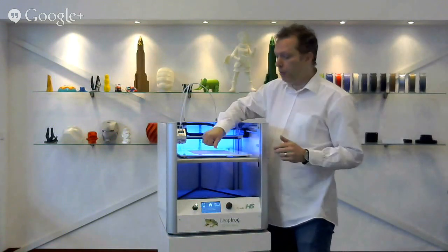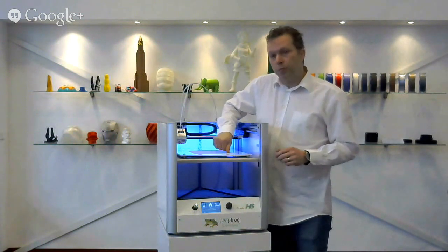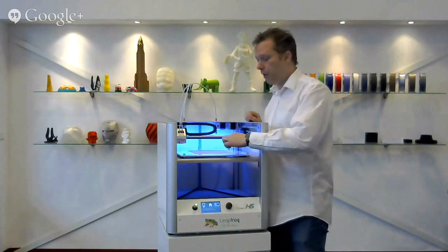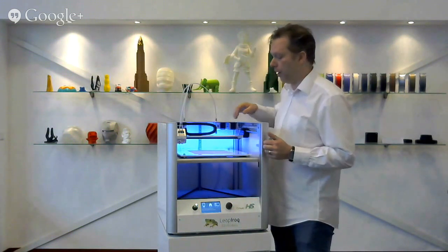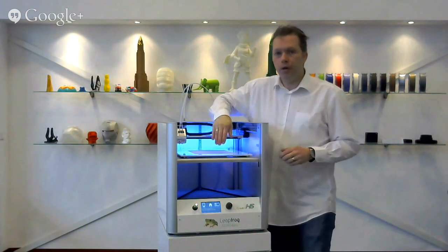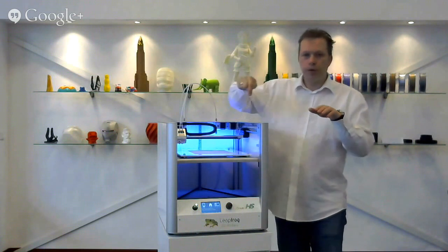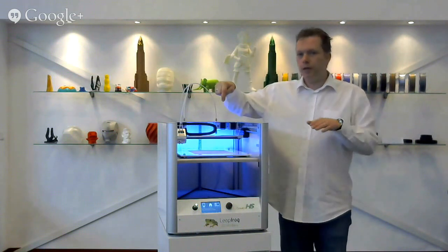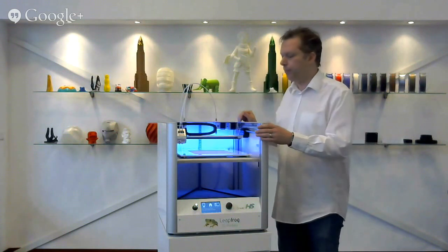If you do get any air bubbles, you can push them outwards. And if you can't push them outwards, you can always cut the air bubble with a small knife and just move the air out that way. Make sure there's no air, because air trapped underneath the sticker will create a bulge. And when printing, especially the first layer, the nozzle will tear up that bulge and will tear up your sticker, and that will mess up your printing.